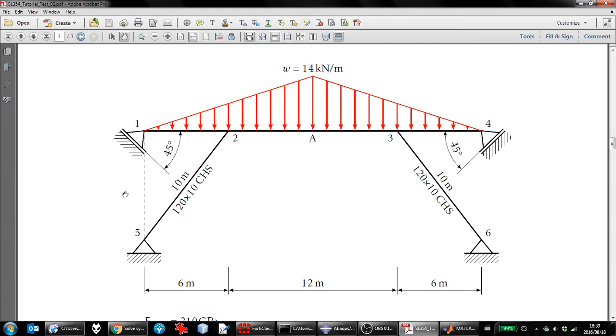That was a little bridge structure. So we had a 6 meter back span as they call it, and then a 12 meter central span with our 10 meter columns. A quick calc to work out that the height of the structure from base here is 8 meters. So 8 squared is 64, 6 squared is 36, which gives us 100. Square root of that is 10.